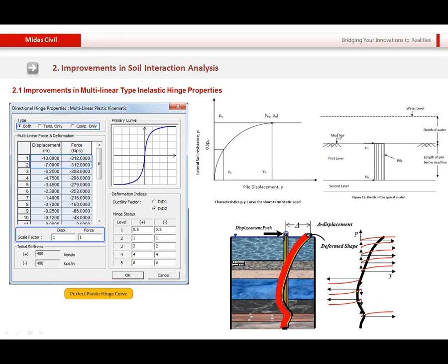The other question is about the geotechnical model. I mentioned that Civil is mainly for the structural engineer, and we have another software, GTS, for the geotechnical engineers. The difference between the two is that Civil can simulate the soils using springs only. Using the nonlinear spring or the linear spring, we can simulate the different soil P-Y curves, as you can see in this dialog box.